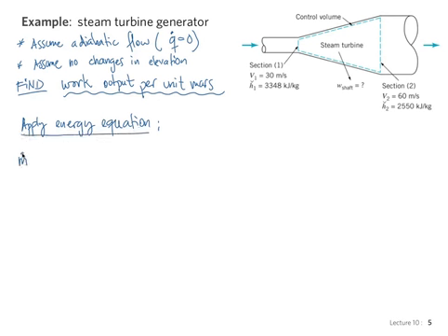We just wrote it down. It was m dot times, I'm going to use the enthalpy now. So the internal energy plus P over rho, we just write h. And out minus in, so h2 minus h1, plus the velocity term, V2 squared minus V1 squared over 2. The elevation we cancel out, so I don't need to write it down.